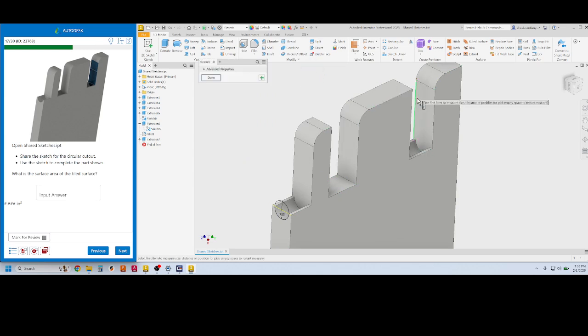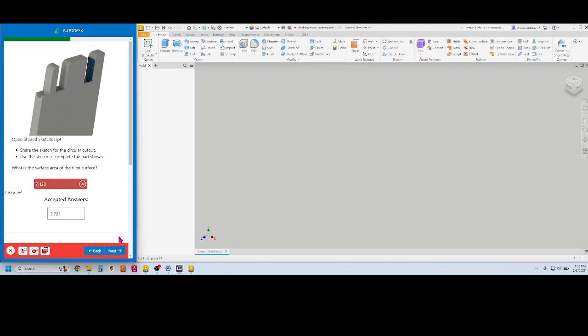Right click in space, measure, select. And we'll go 3 places on this one. It rounds down, so that should be good. Control C, click, Control V. 3 decimal places, I'll say done. Next. Oh, did I put the perimeter in again? Dang it.